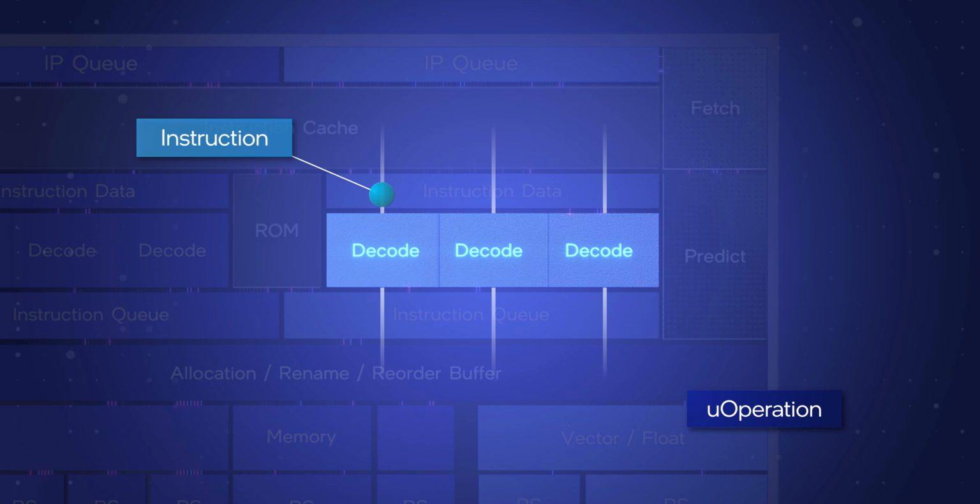ISA instructions often also include additional bits of data that give the CPU more information relevant to the operation, which the CPU uses to decode and execute the instruction in an efficient way according to its microarchitecture. Microarchitectures are typically built so that most instructions map directly into a single UOP, but not all.